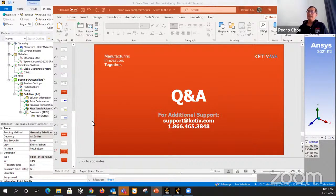You have the A, B, and D matrices, which would be the stiffness in extension, bending, and shear, and then use all those terms to assemble the element stiffness matrix. So basically, the information that you use for each layer will calculate the stiffness for each layer, and Ansys will combine the stiffness for every layer to give you a single element stiffness matrix.